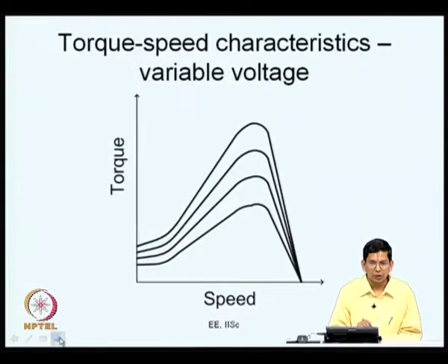See, with a voltage source inverter you are capable of varying the amplitude and applying a variable amplitude on your motor. So, as V decreases, your torque speed characteristic changes like this. For a higher V, the peak torque is high, for a lower V the peak torque is low. So, the characteristics roughly look like this now. So, there is a certain amount of speed control that can be exercised, as we saw in the previous class. If you have a load torque, the torque speed characteristic of a load is a flat line like this, the point at which it intersects now changes with your applied voltage.